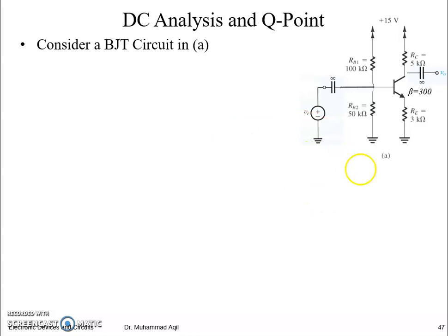For example, for a 5 millivolt signal, if this amplifier is giving a gain of 100, then the output will be 0.5 volts. So the design engineer, like you, has to set a gain of 100 if you want to sell or design this amplifier for a user who requires a gain of 100.